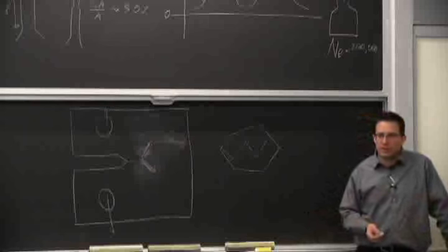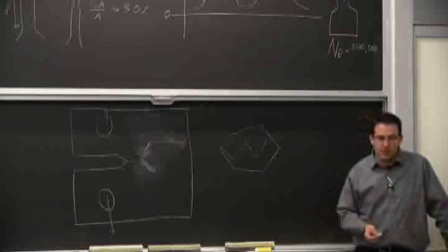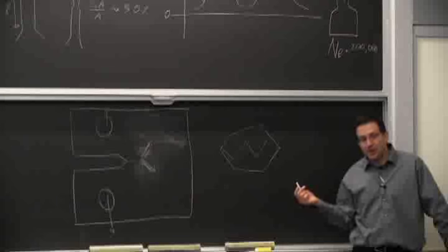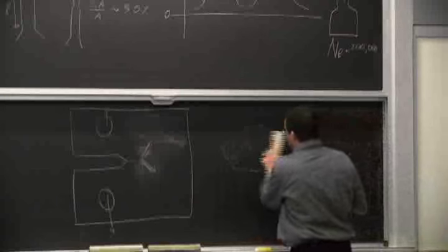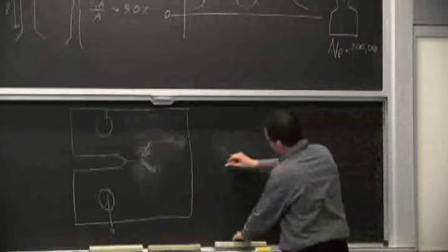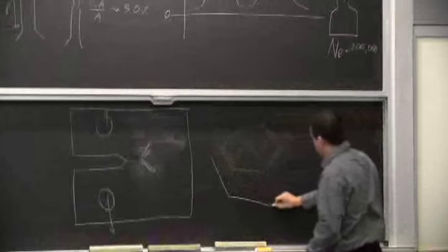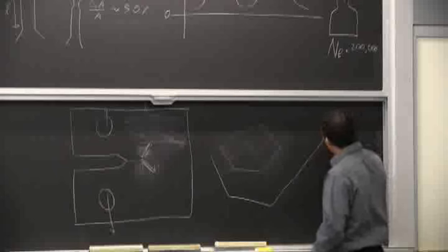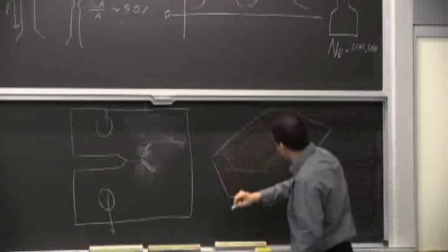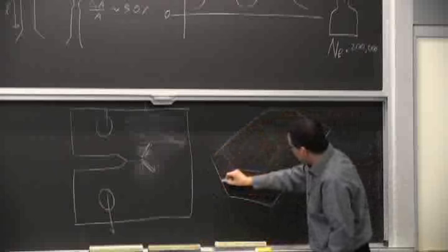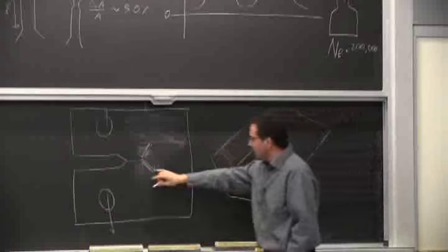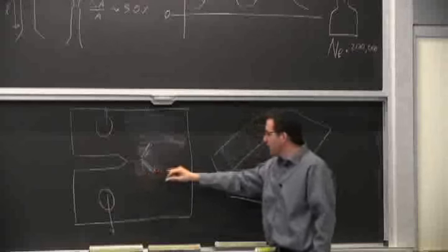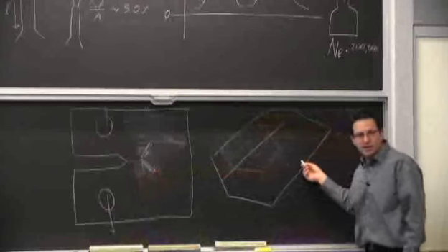And it's also something we discussed in the intro, that at that point, big grains is good, because say my crack wants to go in a grain that's oriented this way. There you go. My crack wants to go this way inside the grain, but really when I'm at the level of the sample, my driving force would like to bring it this way.